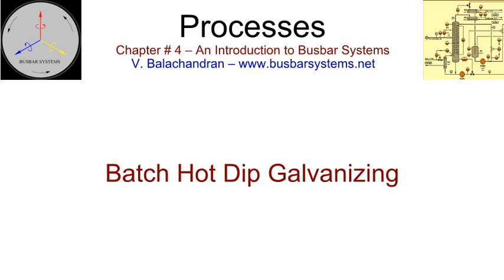Surface preparation of the job, just before galvanizing, is important. Rust, grease, and other foreign objects have to be removed. Some applicators have pickling and rinsing baths. Most of the applicators resort to shot blasting, which is also the preferred mode. It is necessary to carry out the galvanizing immediately after surface preparation to prevent oxidation.